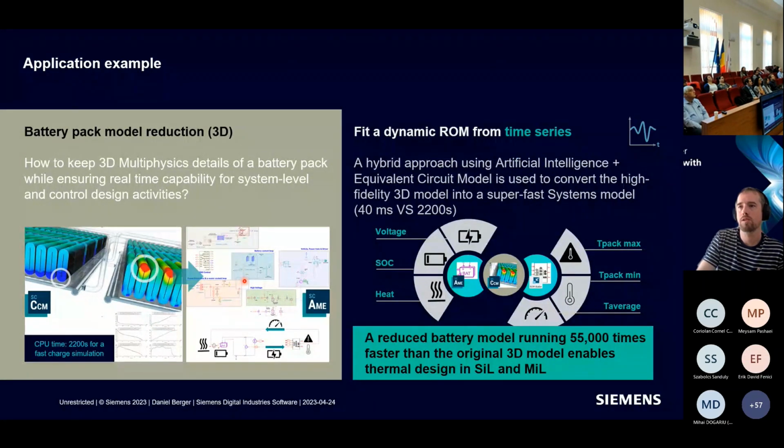Another example is not 1D simulations, but 3D simulations, where you make a reduced order model of a thermal simulation of the battery packages. It is physically more sound information, so to say, closer to ab initio. So really where you solve the physical differential equations to get the behavior of the system. You can make a reduced order model for this, and you are obviously much faster, because thermal models or computational fluid dynamics are so expensive if you really want to calculate this.